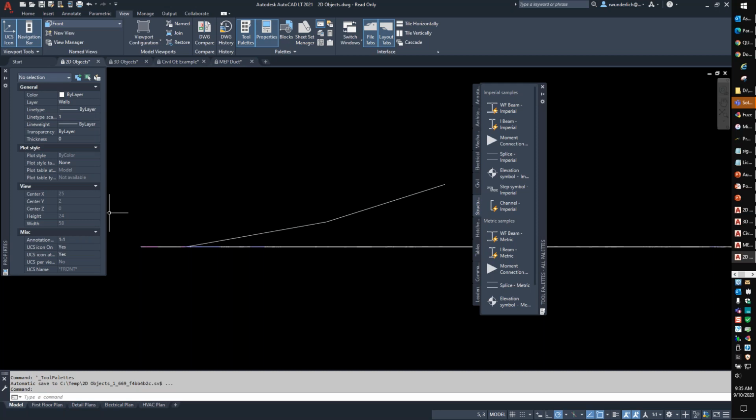Nope, sorry. Is there a Revit LT that matches up with AutoCAD LT? So yes, there is Revit LT. The big difference between Revit LT and full Revit has to do with, again, the same lesser technology. You don't have the ability to run some add-ons and things like that. You can't do worksharing sets, and you can't create to BIM 360 collaborative. But other than that, Revit LT looks and acts and behaves very much like standard Revit.